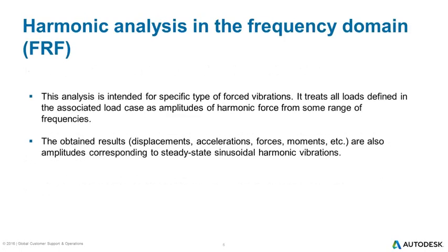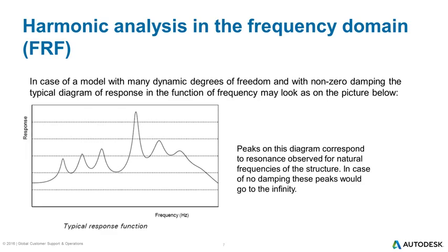A harmonic analysis in the frequency domain, FRF, corresponds to forced vibration of a specific type. It treats all loads defined in the associated load case as amplitudes of harmonic force from some range of frequencies. The obtained results, such as displacement, acceleration, forces, moments, are also amplitudes corresponding to steady-state sinusoidal harmonic vibrations. In case of a model with many dynamic degrees of freedom and with non-zero damping, the typical diagram of response in the function of frequency may look like the one on the currently displayed slide.